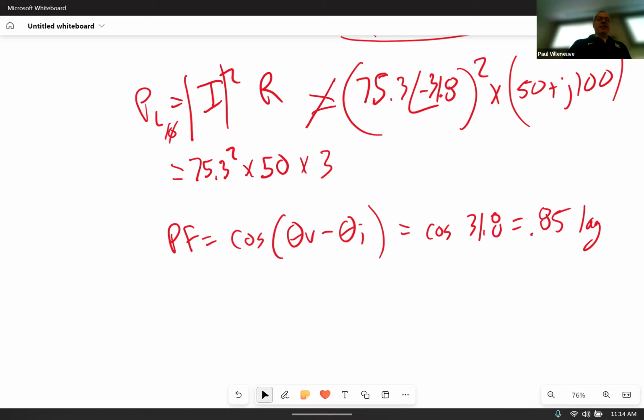It has to be single phase because this is a single phase resistor, right? So I run the current through the resistor, square that, multiply by R, and because I've got 3 resistors, I've got 3 transmission lines, the total power loss is 3 times that value. But you use I line and not I phase. Absolutely. I use I line and not I phase.